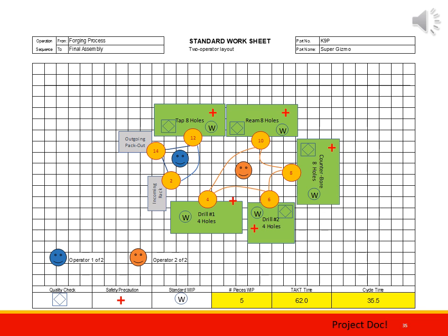So this single piece of WIP is kind of like a tax, right? Yes, it is waste-ish, because I've been hammering on WIP, and WIP is waste. It's one part. But this one part, when you walk in, every operation is started and running, right? Because right now, if there's no WIP in there, operator 2 has to sit there and wait for the holes to drill, right? Assume there's an auto eject.